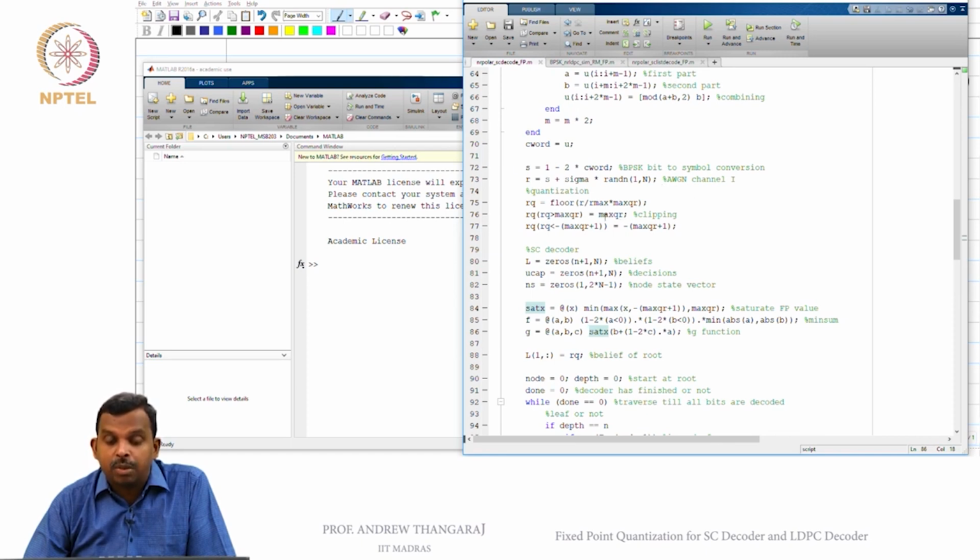So you have to make sure the received value becomes an integer. The saturation effect is something you have to watch out for. And if you're doing any operations in your decoder which increase the value, you have to saturate again. Sometimes when you saturate like this, you have to pay some attention. For instance, in the LDPC code, there are two types of values. One is the LLR for the messages, the other is the LLR for the total LLR. These two are saturated at different levels. They have to be saturated at different levels, otherwise your decoder will fail. I'll comment on that next, but this is something important. When you do operations where you're expecting the value to grow, you have to saturate.